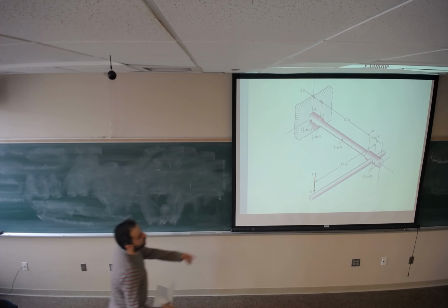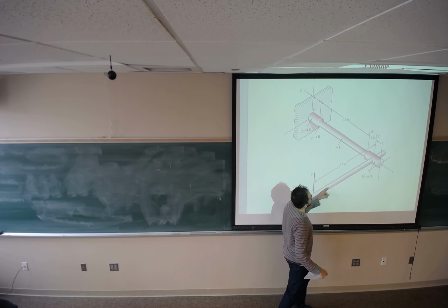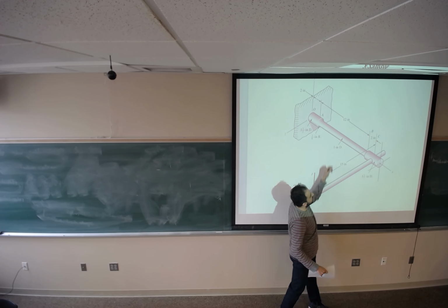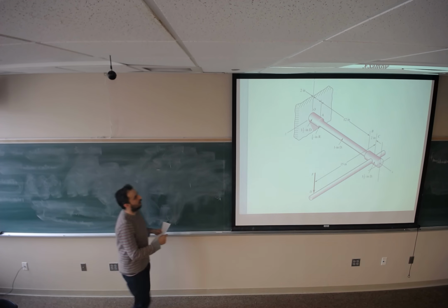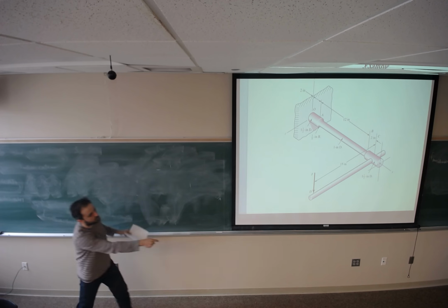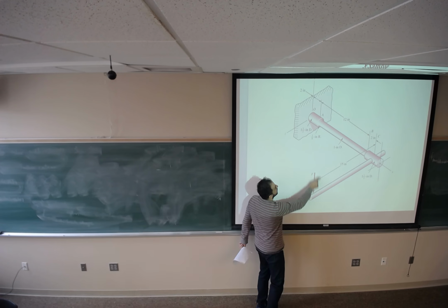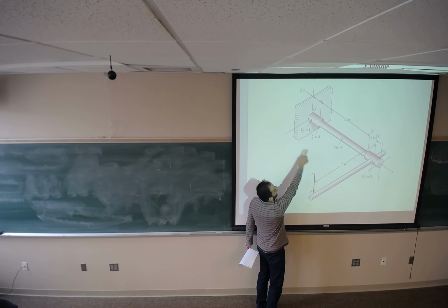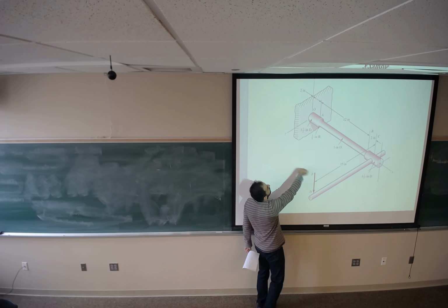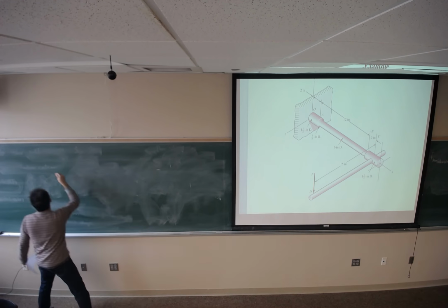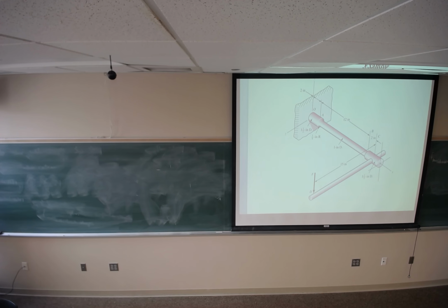This force is in y direction, the distance is in x direction, the moment should be on the other direction. Or you can imagine when you push the force here, it's going to rotate handle AC in Z direction. So MZ at section A is going to be 14 times F.